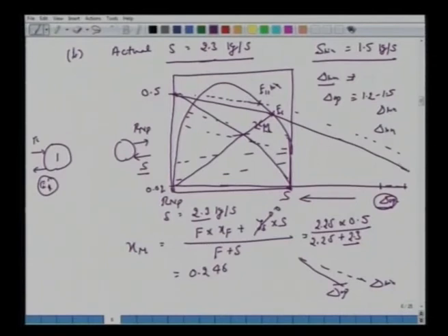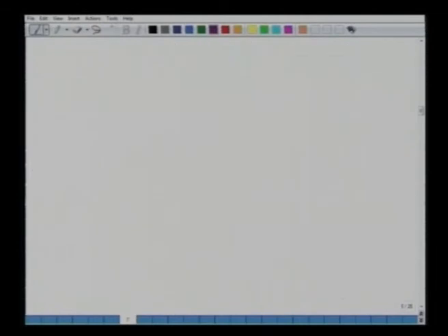So again, let's recall our discussions that the location of the del moves when you take a larger amount of solvent in this direction, till the line connecting this F and E becomes parallel to this. So that means we have reached minus infinity. If you take more amount of solvent, then the del point comes on the right hand side, plus del. Take more amount of solvent, then you have del moving in this direction.